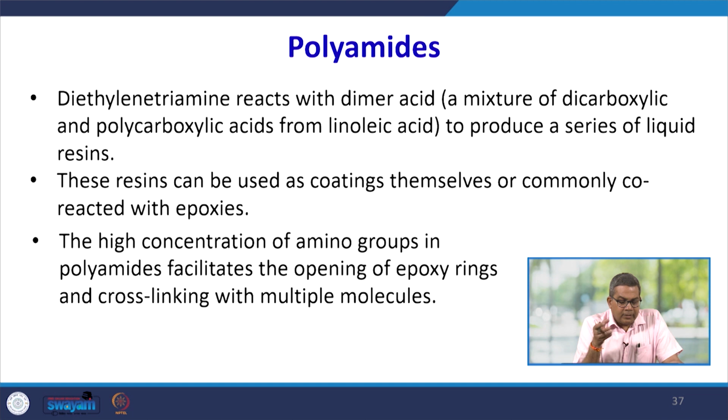Diethylene triamine reacts with the dimer acid, a mixture of dicarboxylic and polycarboxylic acids from linoleic acid, and this produces a series of liquid resins. These resins can be used as coatings themselves or commonly co-reacted with epoxies.